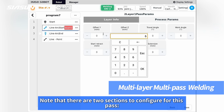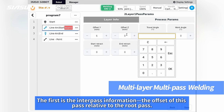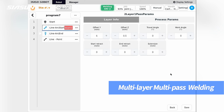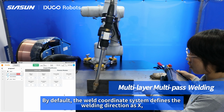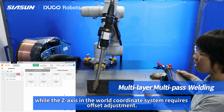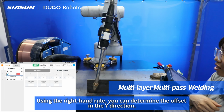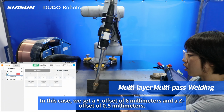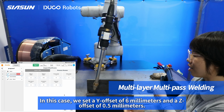Note that there are 2 sections to configure for this pass. The first is the interpass information, the offset of this pass relative to the root pass. By default, the weld coordinate system defines the welding direction as X, while the Z-axis in the world coordinate system requires offset adjustment. Using the right-hand rule, you can determine the offset in the Y direction. In this case, we set a Y offset of 6 mm and a Z offset of 0.5 mm.